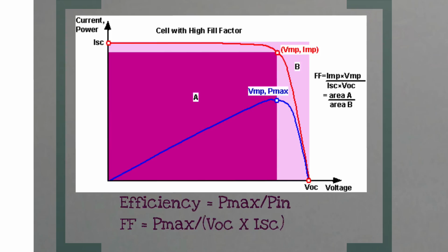It looks like that. At 0 voltage, you get a current which is referred to as the short circuit current, ISC. At 0 current, when there's nothing drawn from it, you get what's called the open circuit voltage. So this is when you have an open circuit. Those 2 numbers are very important, and if you look at a solar cell, pretty much that's what's characterized.